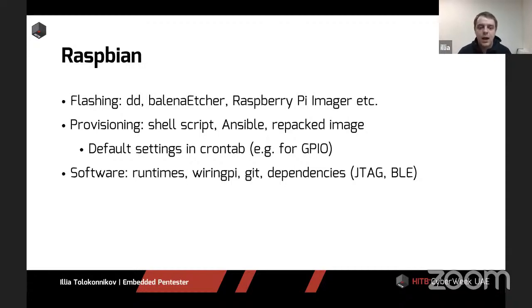And then WiringPi, this is just the utility to control the whole pin header on the Raspberry Pi. We use that instead of a programming language library, say like RPi.GPIO, because we sometimes log into the Raspberries and do things from the command line. WiringPi is really good as a command line utility, and you can just wrap it into some kind of subprocess call if you need to use it in your programming languages.